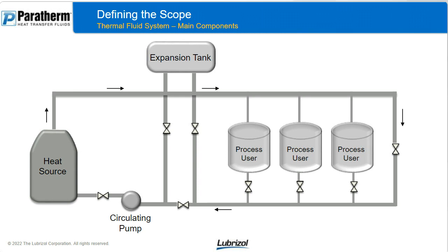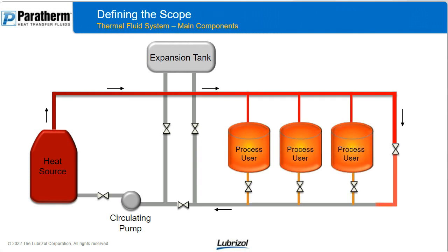So from there, you have heat transfer fluid possibly running through a coil most often, and that is pumped through a pipe. So that brings us to our second main point, which is going to be the circulating pump. You have to have a circulating system in order to get efficient heat transfer. So in a closed-loop system, a circulating pump, whether a centrifugal pump or some kind of positive displacement pump, is usually what you're going to be running into most, but the fluid has to be moving.